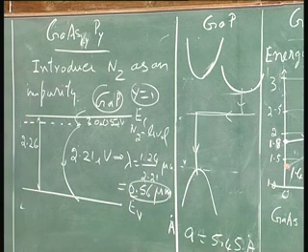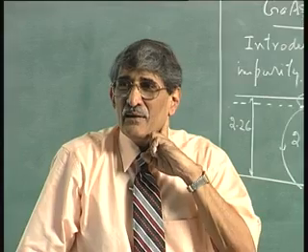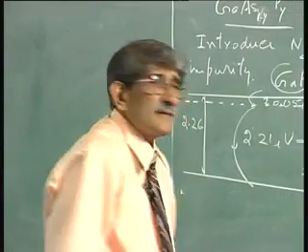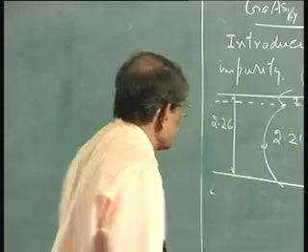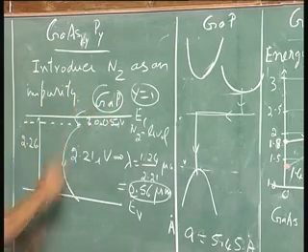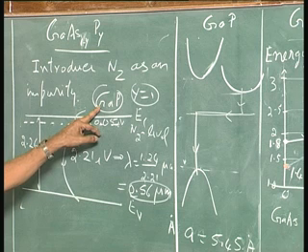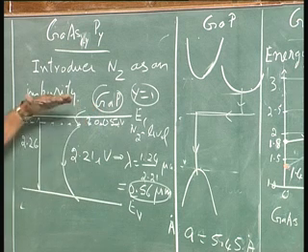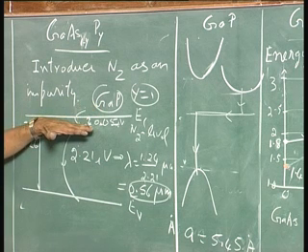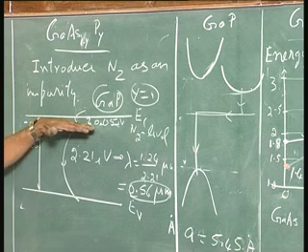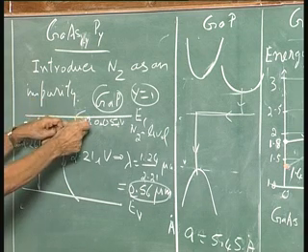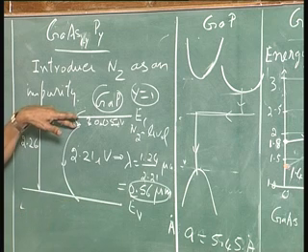What is that? Anybody guess who is an expert in wavelength? It is green. So, you can make use of gallium phosphide, which is an indirect bandgap semiconductor, add an impurity like nitrogen, which introduces a level 0.05 electron volts below the conduction band, force a transition through that and force the emission of light.